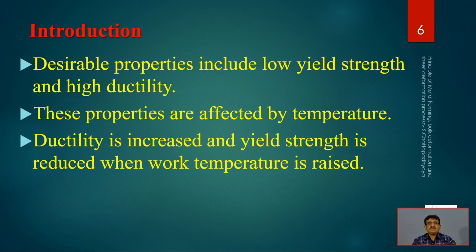So temperature has a very, very important role to play, and because of that, we have two very important classifications. One is hot forging and the other one is cold forging. The recrystallization temperature differentiates those two processes from one another.